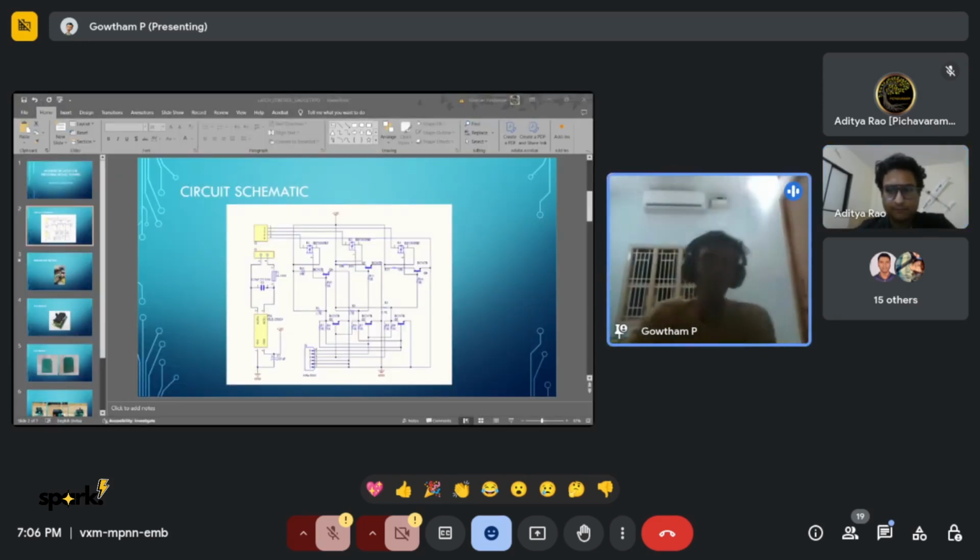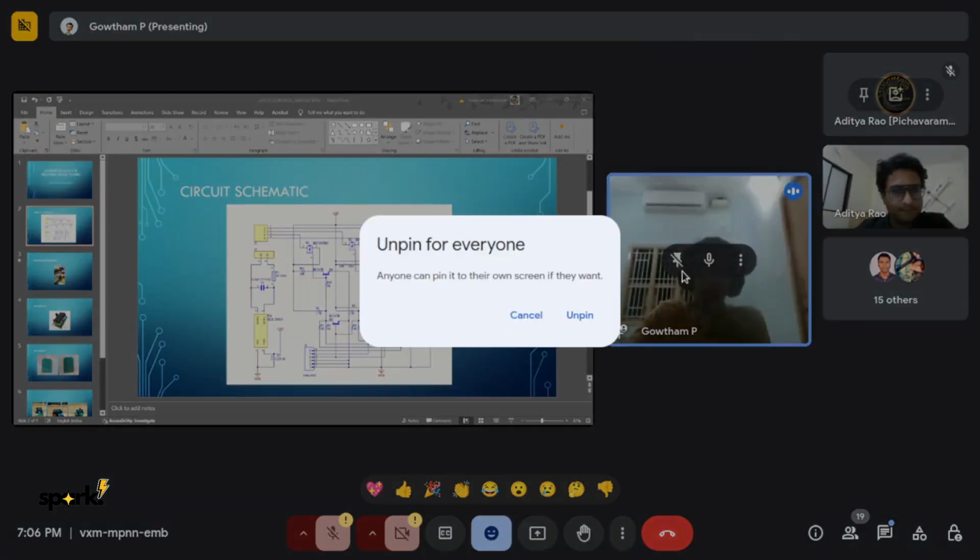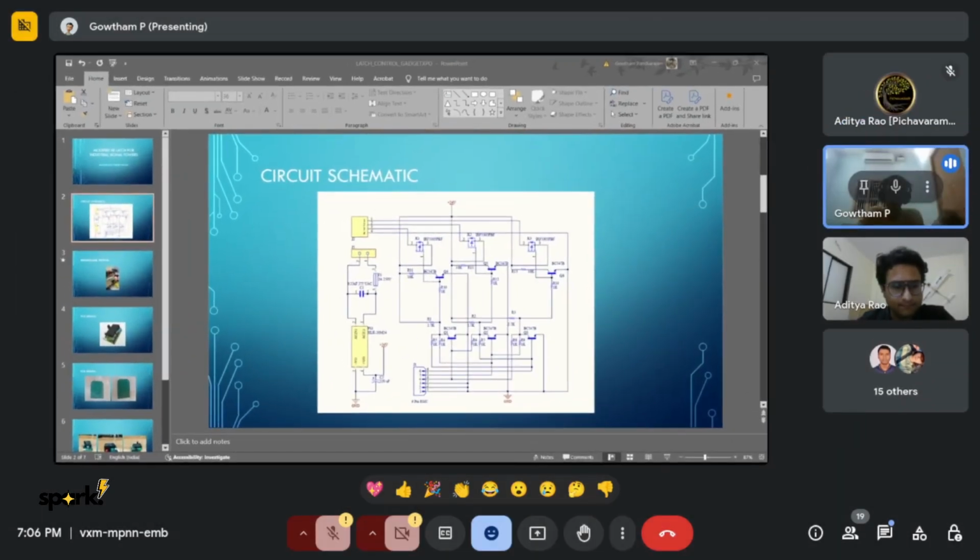In an SR latch, the collector of one transistor is connected to the base of the other transistor. So when a transistor switches off, the collector voltage will turn on the other transistor. That's the basic concept of an SR latch. Here there are two transistors, so two states are maintained, either on or off. For a single transistor, there is a single state, right?